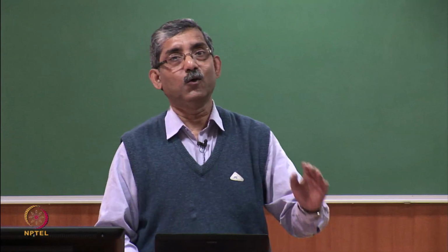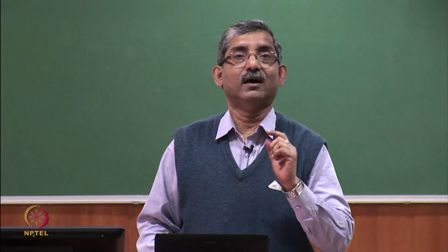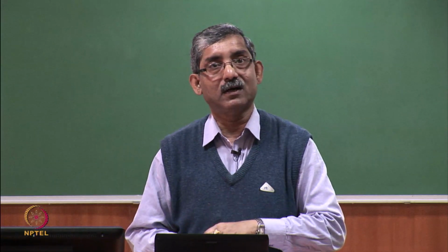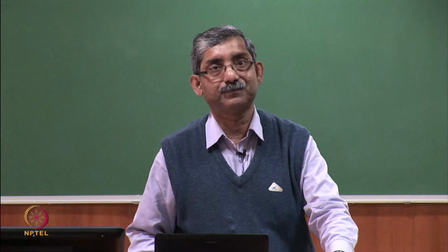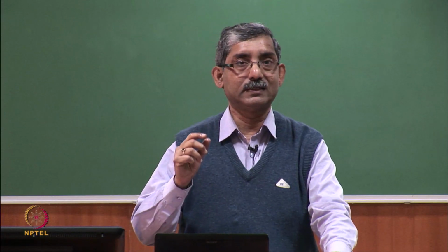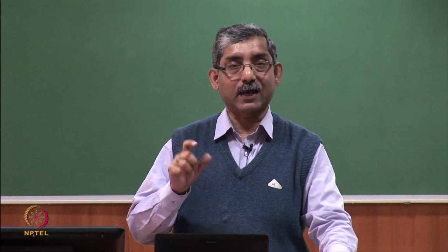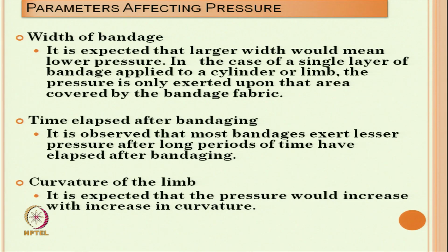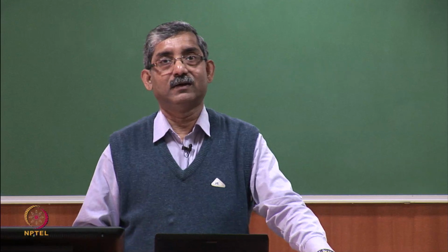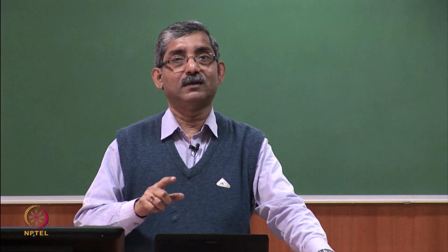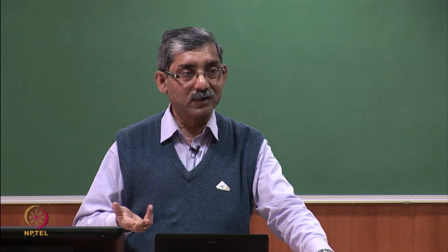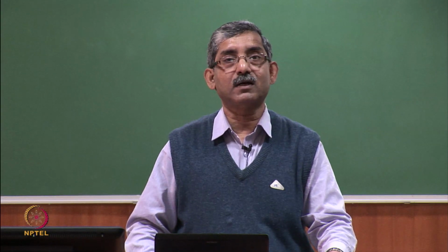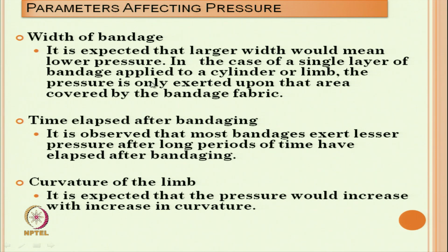So, keeping the load constant, here the load is basically due to the tension during the wrapping of the bandage. If we use a narrow width and another is a wide width, for the same winding tension, the wide width means the effective area will be more. So, accordingly the pressure will reduce. So, it is expected that larger width would mean lower pressure.